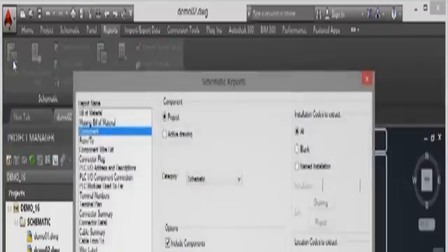There are times when you will need to edit your reports in your AutoCAD electrical drawings before you output them either onto the drawing or out to a separate file format, such as a database or a spreadsheet. So we're staying with Demo 16 project, and we've still got the drawing Demo 02 open, and it's a schematic drawing. So we need to go to the Reports tab here, into the schematic panel again, and make sure we click on the reports icon like so. We're going to go for a component report again, in the active drawing, schematic category, and we're also going to include the children for the above components in the options.